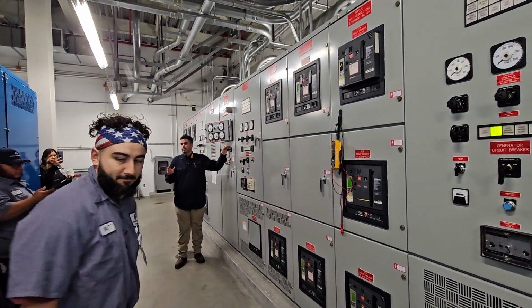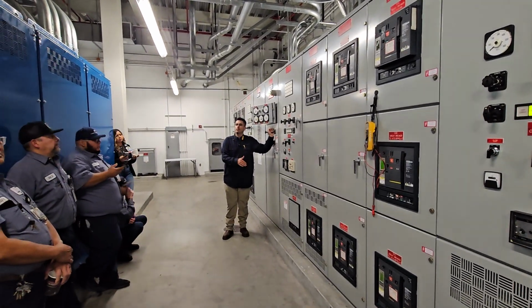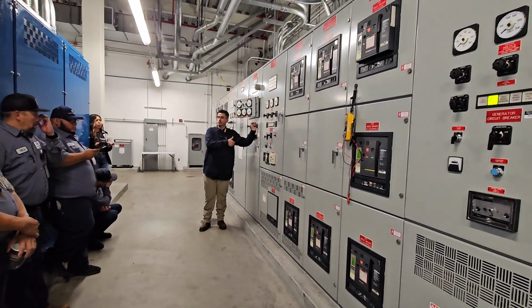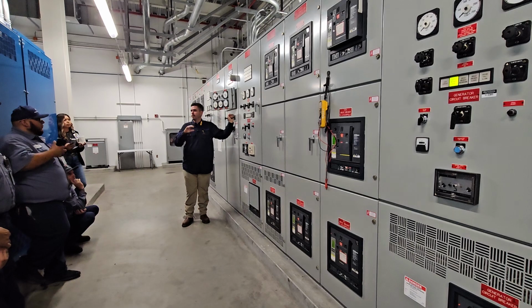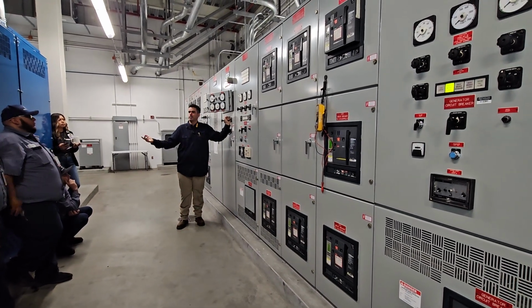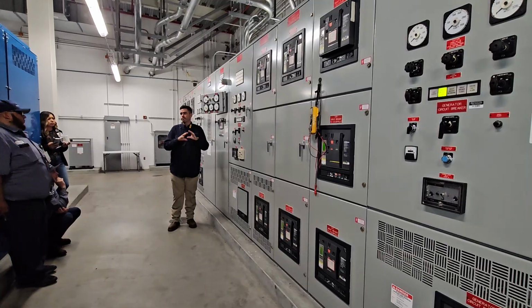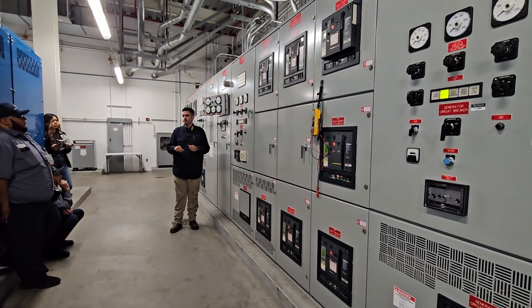The only thing that is gonna happen, regardless if you're in manual or in auto, when under an outage condition, the generators are gonna run, but they're not gonna do anything. They're not gonna close the breaker. They're not gonna send any transfer signals if you lose the PLC because the PLC is dead. So when the PLC dies, the generator is like, okay, I need to kick on because something happened.